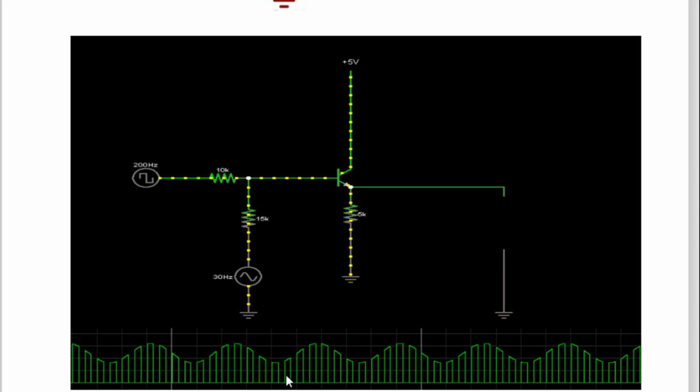And here look at this output at the bottom. You are getting a square wave: HVL, LVL, HVL, LVL, positive edge, negative edge, positive edge, negative edge, positive edge, negative edge. So like that, this square wave has LVL at 0 volt only, but only HVL is changing according to the instantaneous value of the information signal, and this is called the pulse amplitude modulated output, PAM. The amplitude of the square wave, that is the HVL level, changes according to the instantaneous value of the sine wave, and therefore if you join all these points, then you will get the information signal.